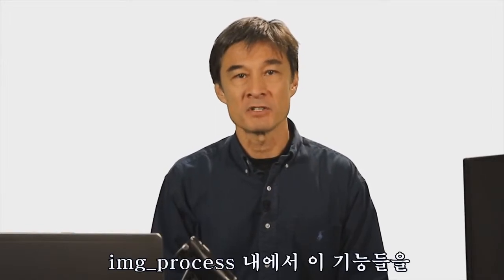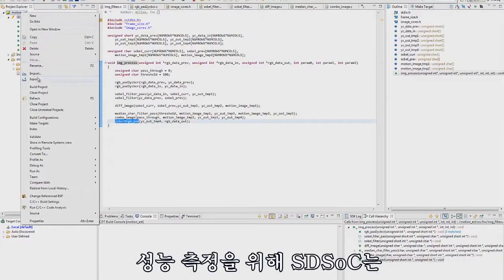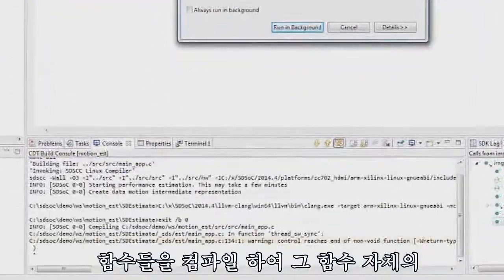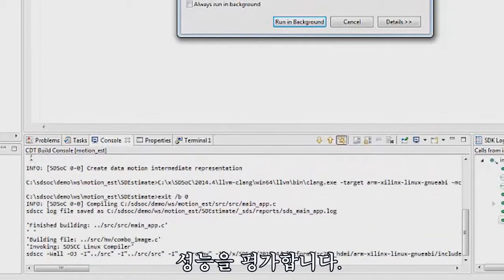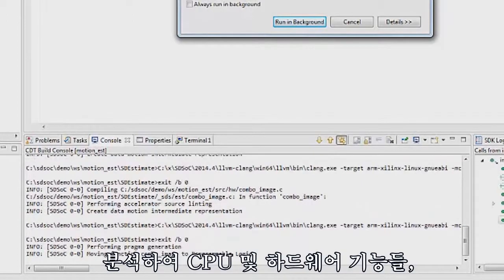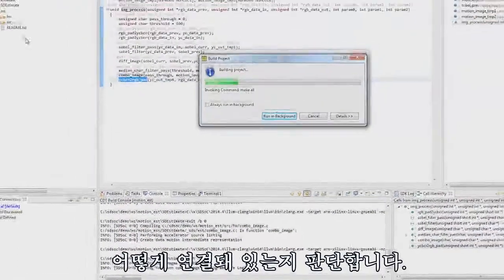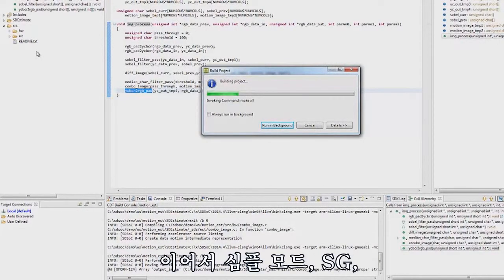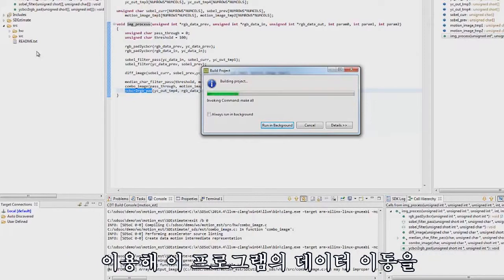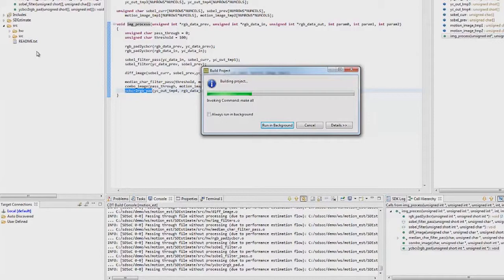We'll mark all of the functions within the image processing pipeline for hardware. For performance estimation, SDSoC first compiles each function selected for hardware to obtain a performance estimate for the function itself. The system compiler then analyzes the program to determine how the CPU, hardware functions, and memory are logically connected. It then determines how best to implement the program's data transport using a library of data movers such as simple mode, scatter-gather, and 2D DMA.